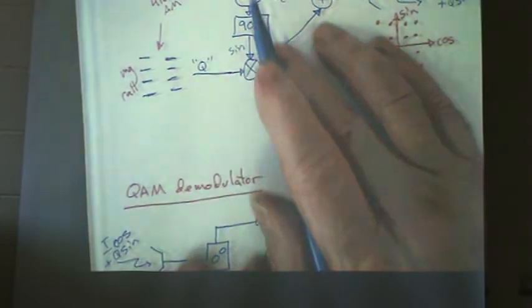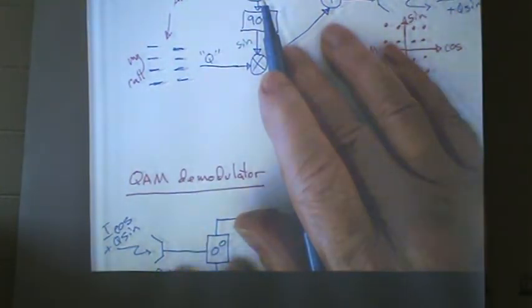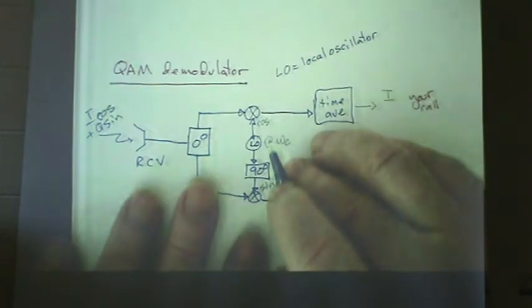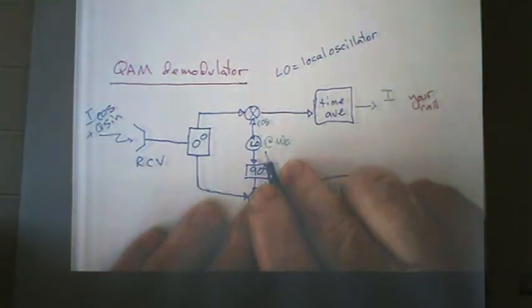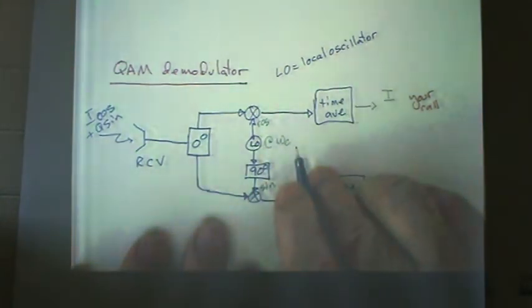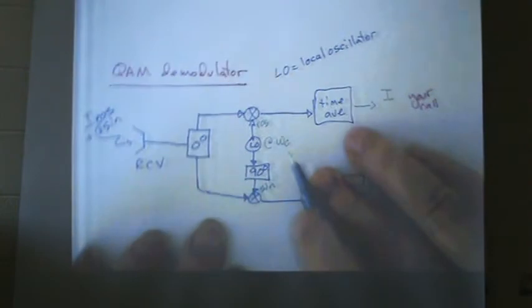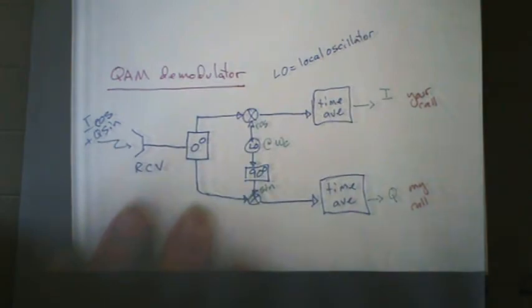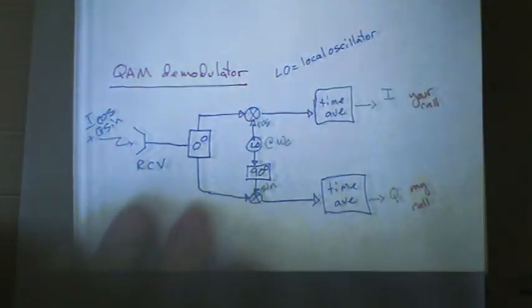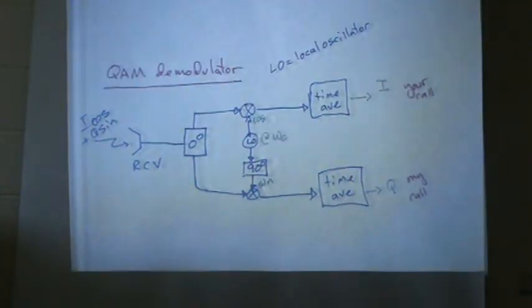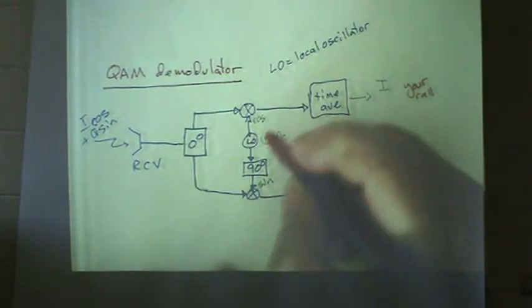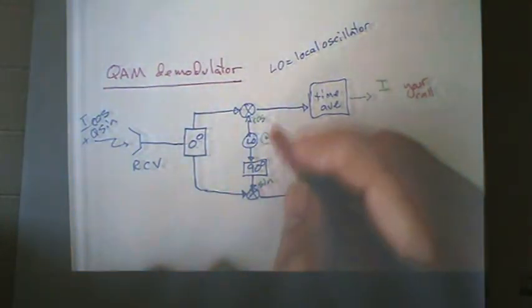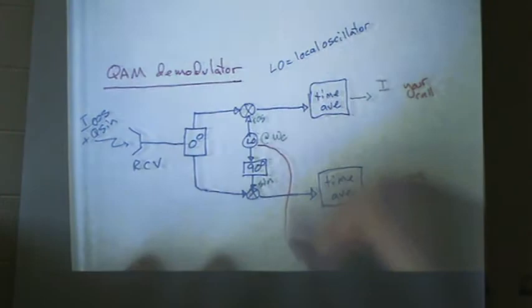How does this oscillator know what time it is compared to this other oscillator? Right? They can drift. They can drift in phase. They could also drift in frequency. How do you know it's 2.4 gigahertz? That little oscillator has a crystal or something that makes it at 2.4 gigahertz. When you change the temperature, it's going to shift a little bit.